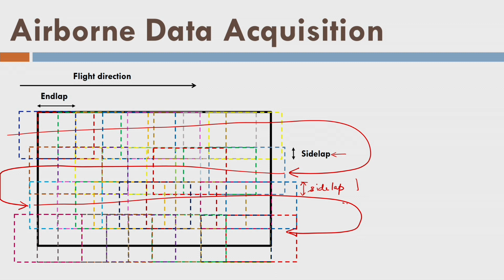So the idea here is, how can I find out the depth, or how can I make the 3D map using photogrammetry. So let us look into that now. But before that, we should understand how many photos are required for a given area. Before we go to the field, we have this area beforehand, that this is the area I want to do 3D mapping for, and hence I want to acquire photographs for this area.